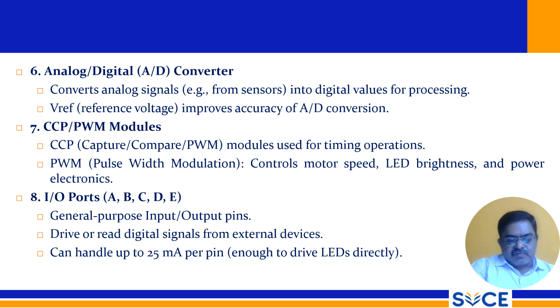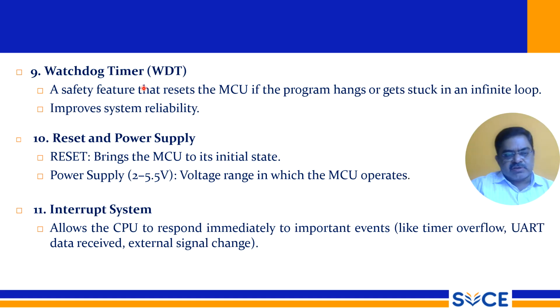Next is the watchdog timer, WDT, a safety feature that resets the MCU if the program hangs or gets stuck in an infinite loop, improving system reliability. And reset and power supply: reset brings the MCU to its initial state, and the power supply is 2 to 5.5 volts, the voltage range in which the MCU operates.